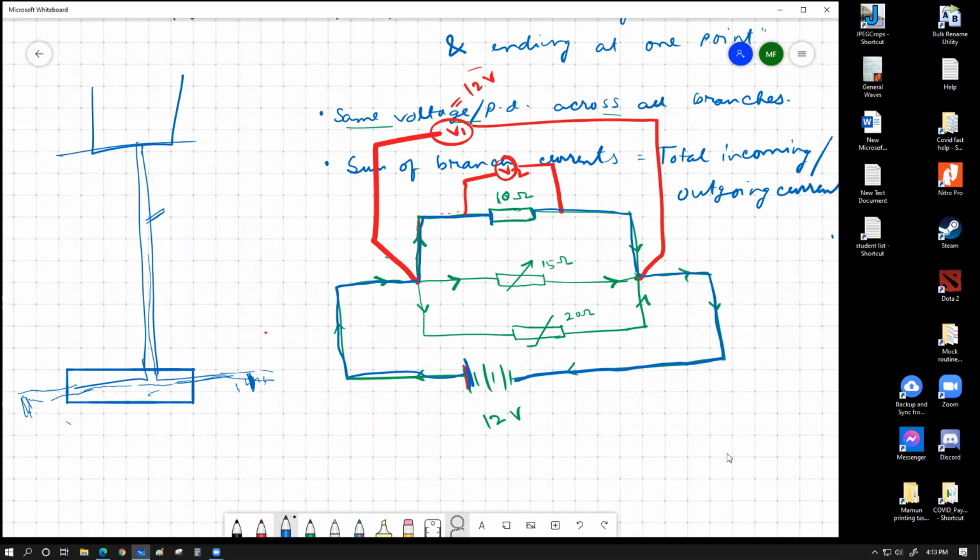You have to understand this thing as well. Even if we allow multiple of these components to allow current flow directly or continuously, these wires, which are considered to be of zero resistance, have the capability to accept an infinite value of current. I mean, 10 ampere, 12 ampere, 100 ampere, 2000 ampere, 2 million ampere, doesn't matter. A theoretical connecting wire is capable of carrying any value of current, which means if this branch carries some current, and this branch carries some current, and this branch carries some current, if you sum up all of these currents, that total current will be coming out through here when all three of these branches are working simultaneously.